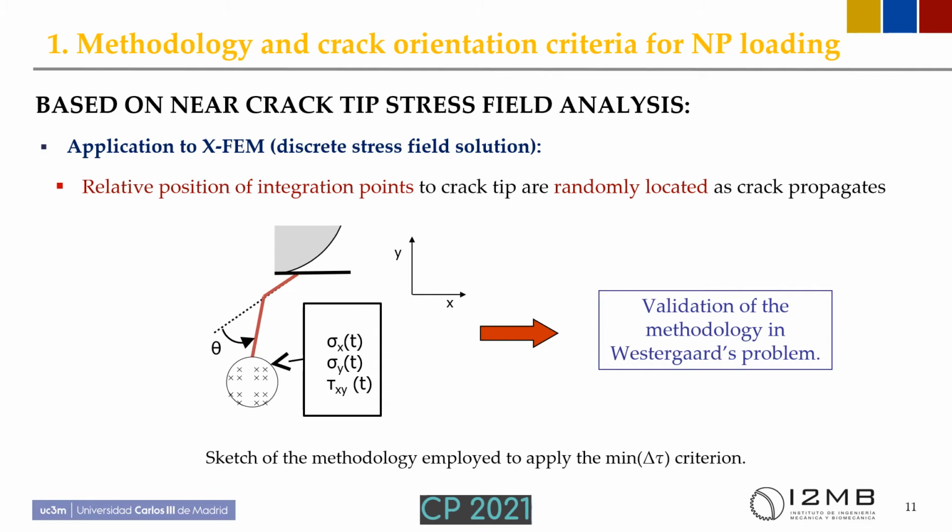We validated this methodology using the Westergaard problem, which has an analytical solution, and thus we compared the results obtained with the two stress field solutions. We obtained quite a good correlation for kinked angles below around 40 degrees.